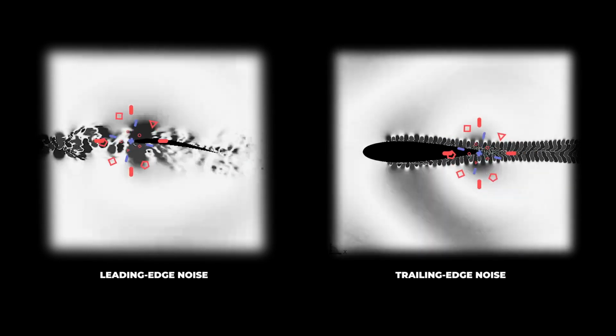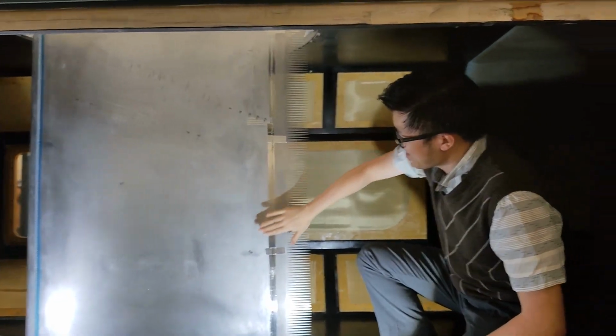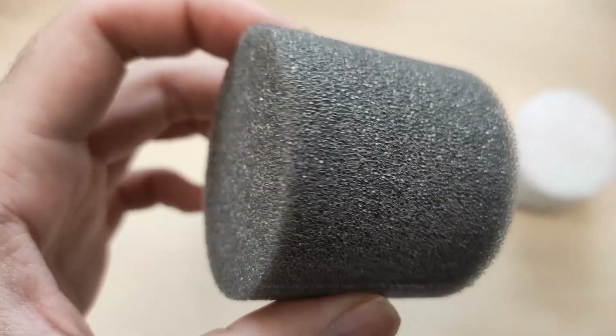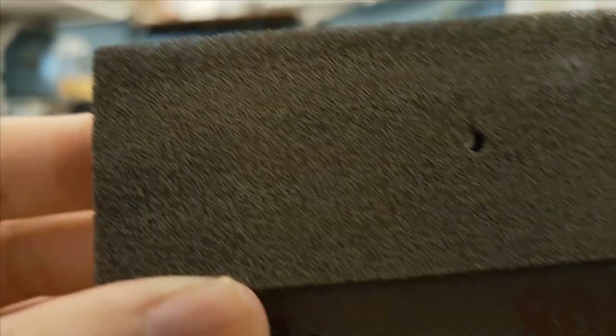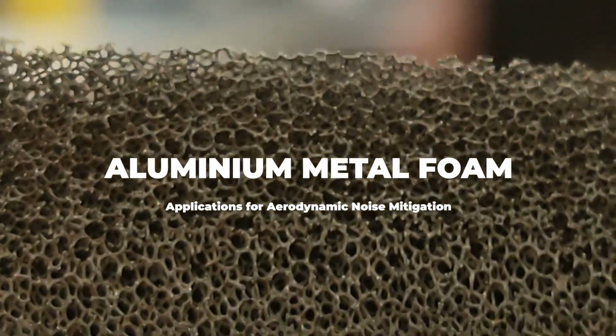As you can see, noise is produced when turbulence encounters a sudden transition in the flow field, from the free fluid to a solid body, or vice versa. Instead, a smooth transition perhaps would help with noise reduction. And fortunately, there is a material that is sort of in between a fully solid or fluid. Those are porous materials. In the following, you will find two applications of this aluminum metal foam for aerodynamic noise reduction.